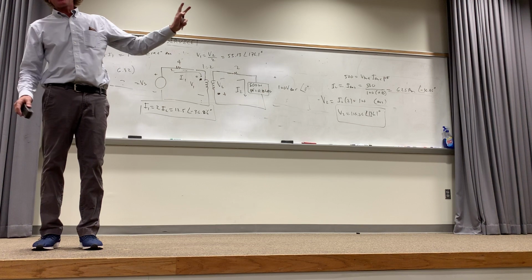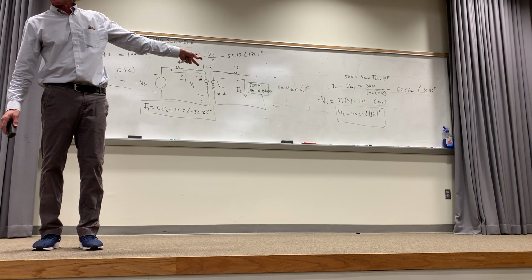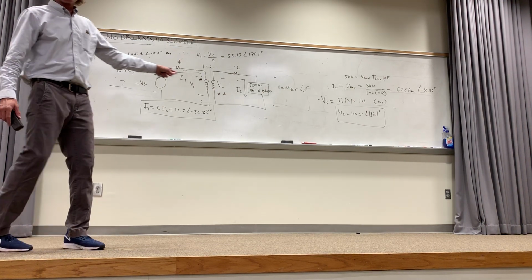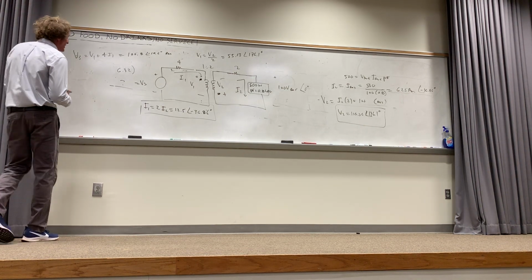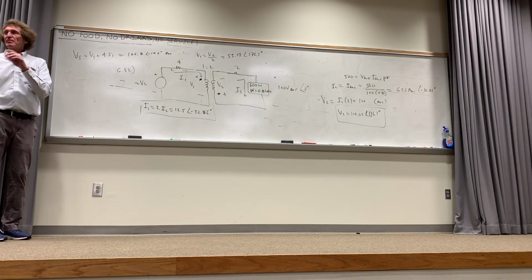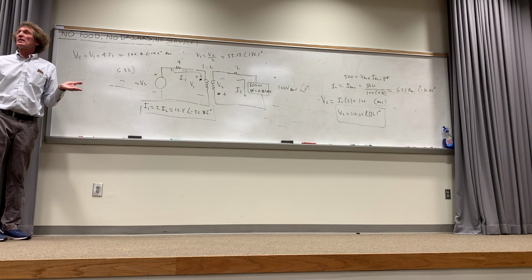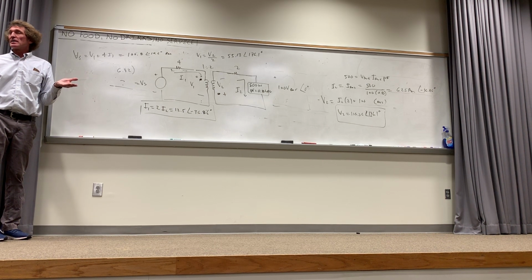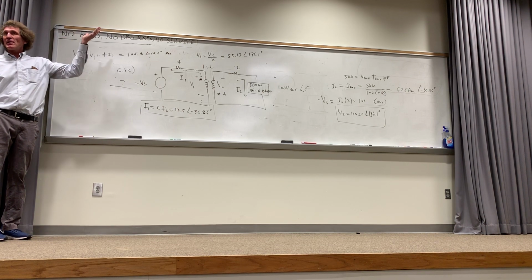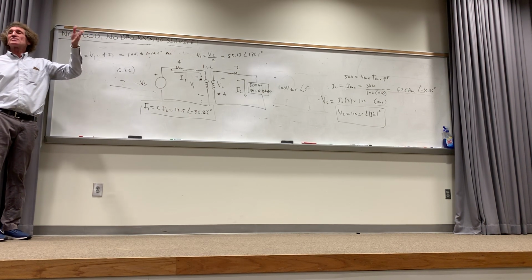Now here you've added the element of power into this, right? And our voltage here is actually a peak, or an RMS voltage. If you wanted the peak voltage, what would you have to do? Somebody, did you say it or not? How many know? Anybody know? Multiply by square root of 2, right?